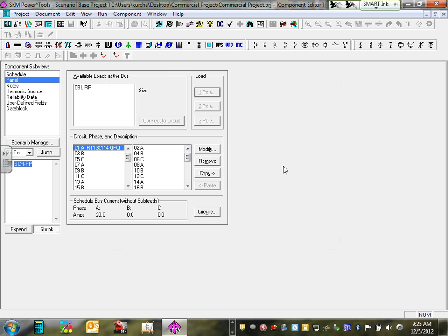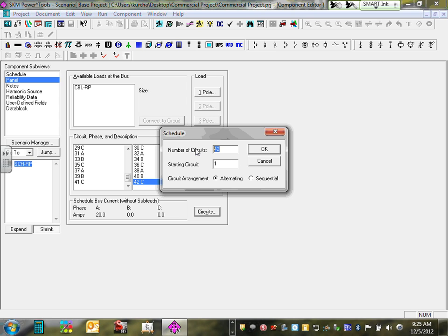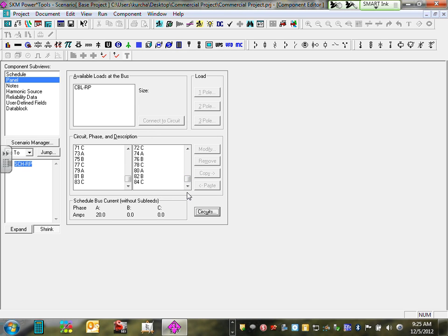Receptacle load. So here, I want to go to circuit number 2, click on 2, you go 4. You can click on any one of these and start filling them, guys, up to 42. If you run out of 42, what do you do? Click on circuits, and for the receptacle panel you have to get 84, so make this one 84 right away. So I have 84 slots to fill. Michelle Cooley Erickson use this software to generate their panel schedules. They don't use Revit for most of their projects; they generate their panel schedules directly from the software. Any questions, guys?